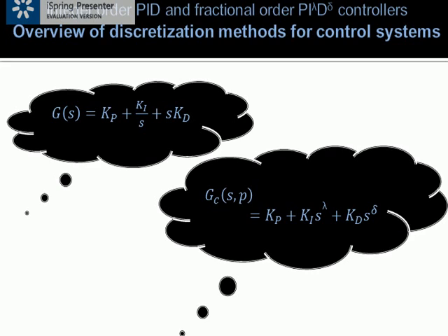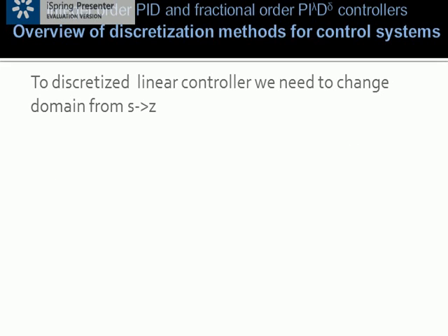The equations shown before are just theoretical. They are not equivalent to the cases of simulation or numerical evaluation of the fractional operators. In the case of control implementation, it is very important to obtain good approximations with a minimal set of parameters. On the other hand, when the number of parameters in the approximation increases, it increases the amount of required memory and processing time too. Because of these reasons, for directly discretizing s to the power r, we shall concentrate on changing the s domain